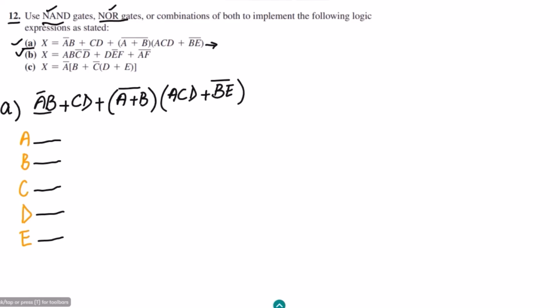So what I have to do, let me deploy here the NAND gate. Okay, so the two inputs of this NAND gate are combined together, and here we will get A complement. Okay, so after this A complement, A complement and B have to be multiplied together. To multiply them, I am going to use another AND gate. Okay, so here this is the AND gate and two inputs are given to it.